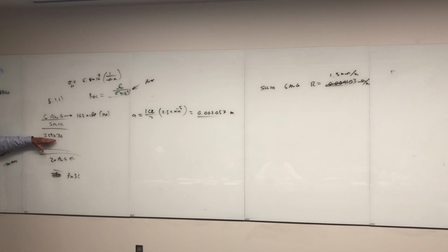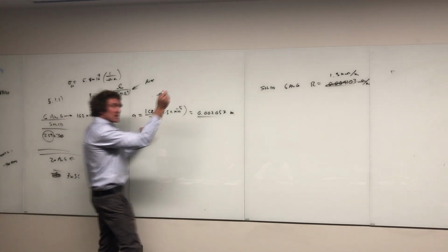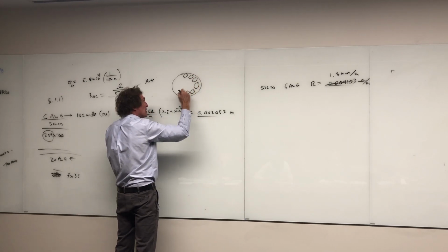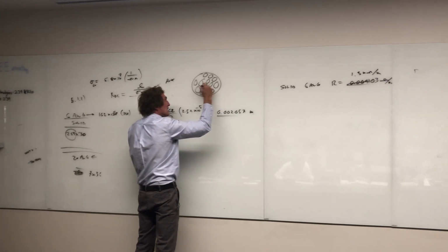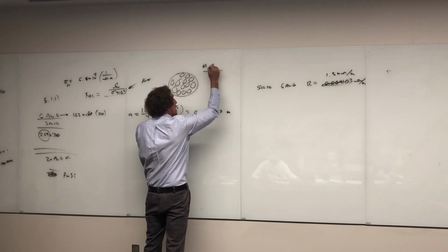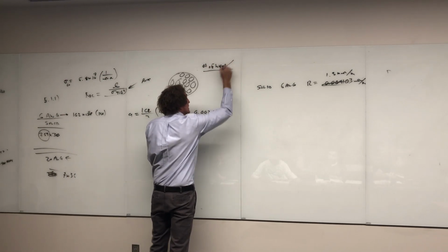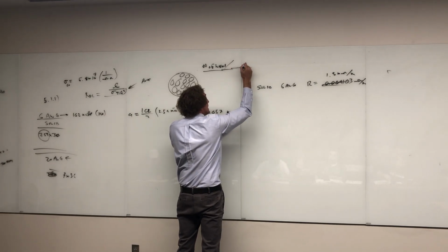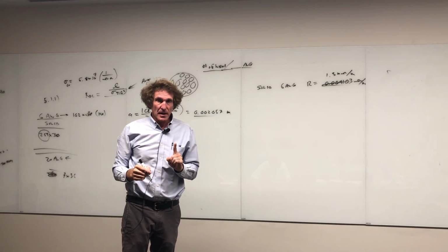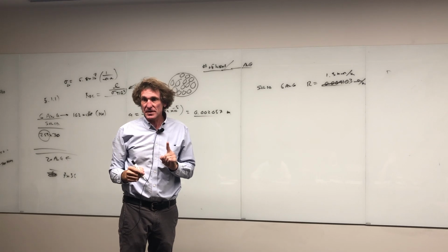By 30, is that what it is? Yes, sir. All right, now here's what happens here. Please listen. The 259 is the number of wires. The first number is the number of wires that are in parallel. Because what it looks like is this. You're going to have a whole bunch of wires that are tightly bound, and this is the cross section I'm showing you. So the first number whenever they do American wire gauge is going to be the number of wires if it's stranded. The next number is going to be the actual AWG rating of one single wire in that strand. Do you follow me?